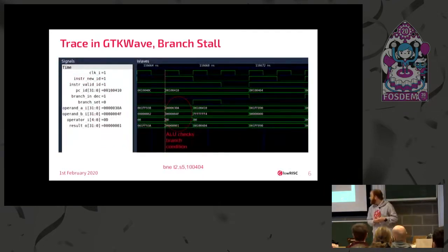And here's a couple of things that I found. The first thing is this example here, which is a conditional branch. You can see the instruction down in the bottom there. It's a branch if not equal, and this particular condition is passing. The thing I have in the red circle there is the first cycle of us executing this branch. We've pulled the two operands out of the register file, and lo and behold, they are not equal. So our result there is a positive, so we are going to branch. But before we can branch, we have to work out where we're going to.